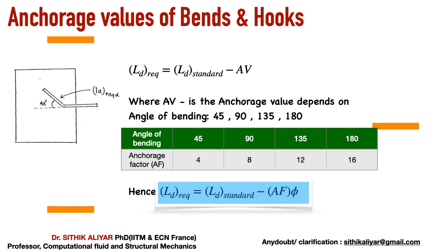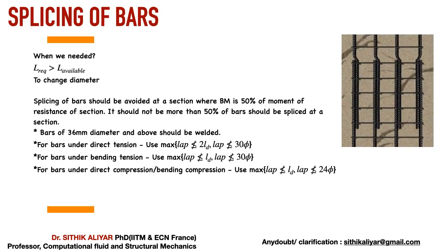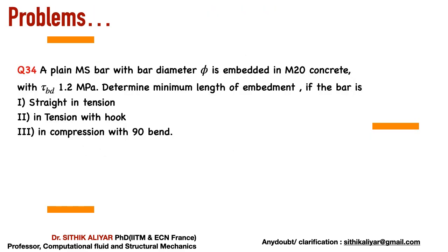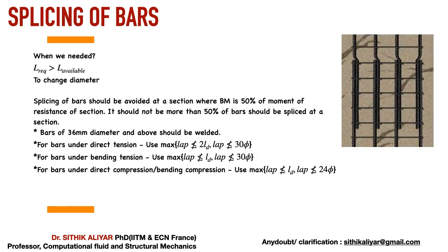The question from this chapter will be related to development length required. Okay, development length required should be equal to development length standard, that is based on this formula, minus AIF into phi. AIF is nothing but this anchorage factor. Okay, to make sure you understand all these 3 formulas, I will show some examples from 2 slides. Okay, so I will give some more 1 marks.